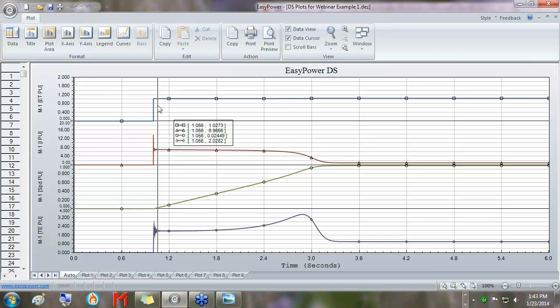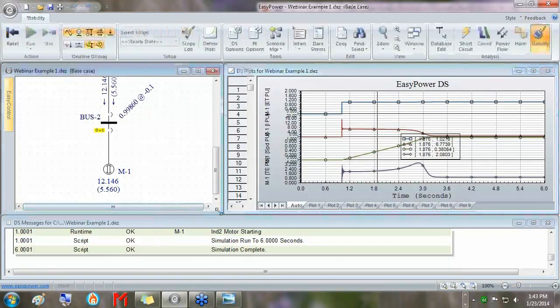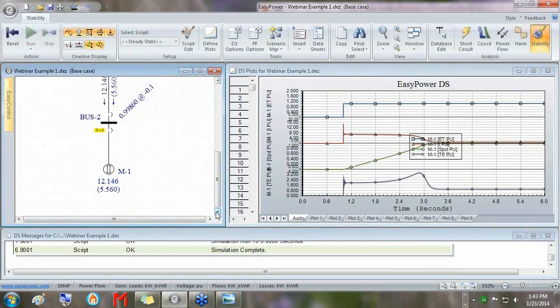And that is true. If there was nothing on that bus before and this is a very light load, your voltage is going to be roughly 1 per unit, which is 480 volts, not 460. That's a nice little interesting thing to note.